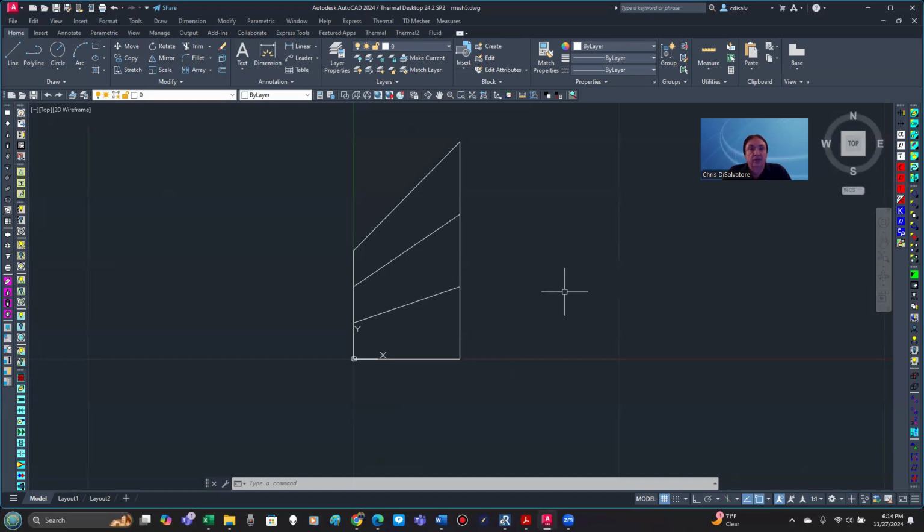Now, there's another way to generate the surface. I can go ahead and delete this one. And it's going to be the edge surf command. And you can use that when you have a feature that is defined with a contiguous line around the edges. So I'll go ahead and create that in this situation.